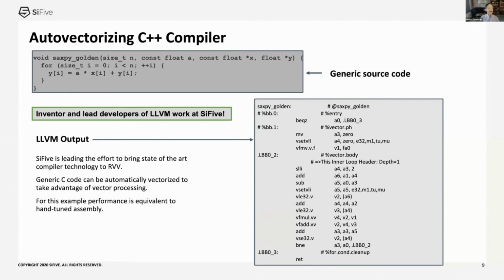Does RVV have any AI-specific operations? At this point, we designed RVV 1.0 to be a very general vector instruction set to support many operations. A lot of AI is very generic operations. For example, we could say we had ReLU support, but in fact, that just means we have a max instruction or a min instruction.